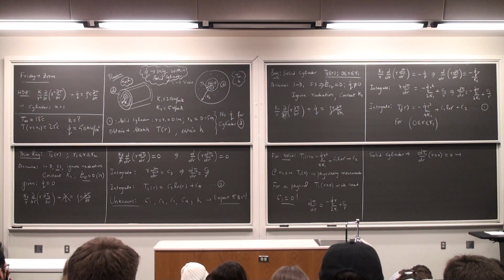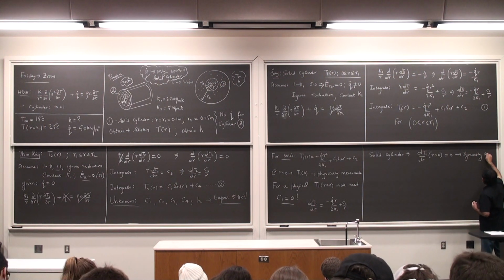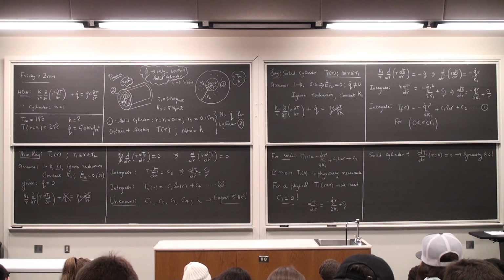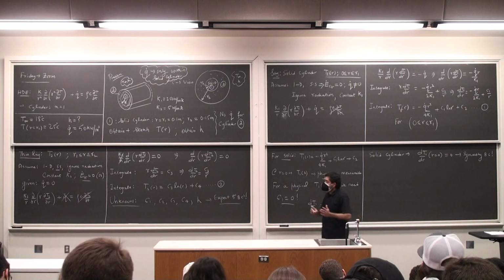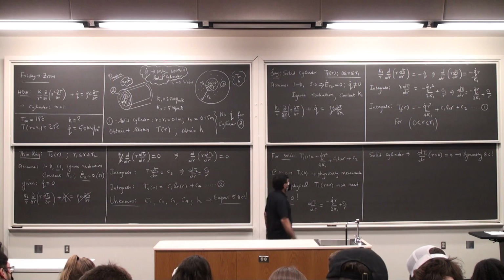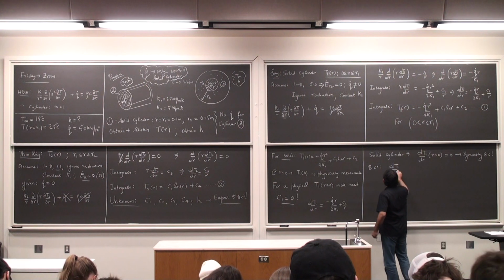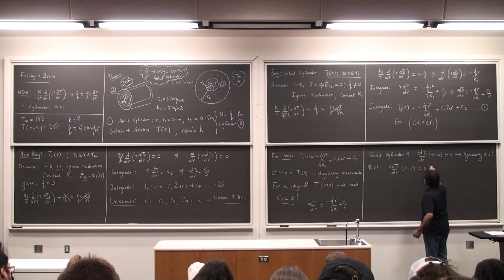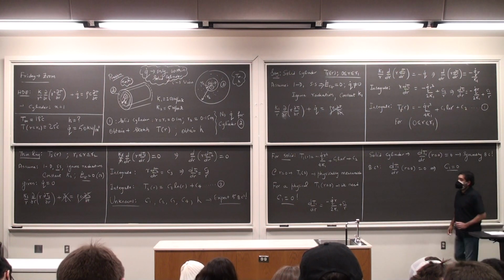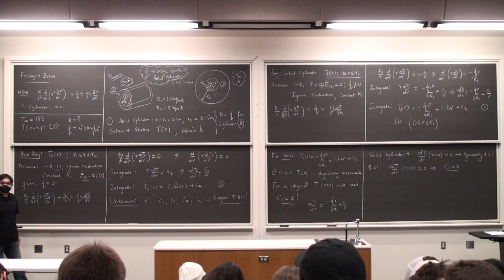Okay, this is called the symmetric boundary condition. We discussed this last time. So this is the first boundary condition. So if you see a solid cylinder, your first boundary condition is dT by dR at R is equal to 0 is 0. Okay. Which implies that C1 is 0, so we have obtained the first constant. So I'm done with C1. I need 4 more conditions.